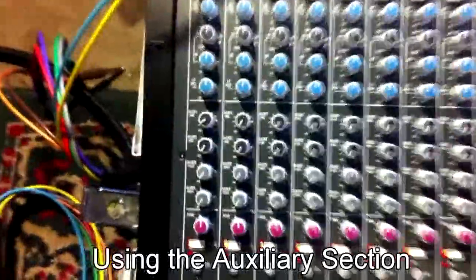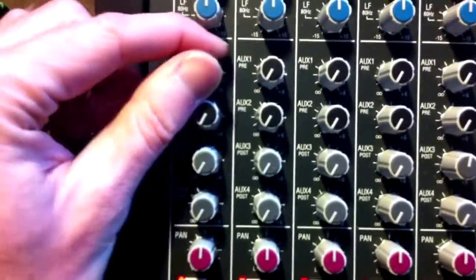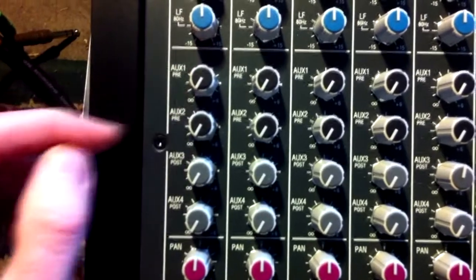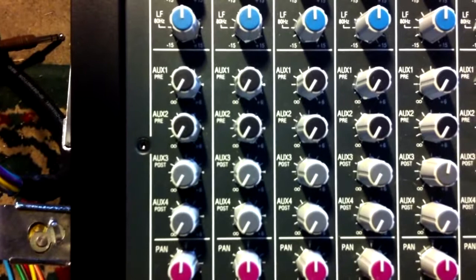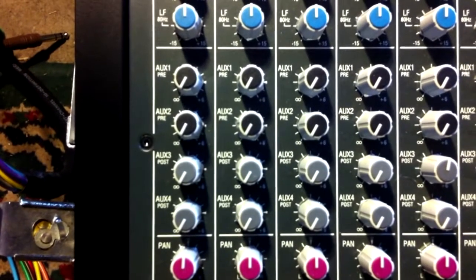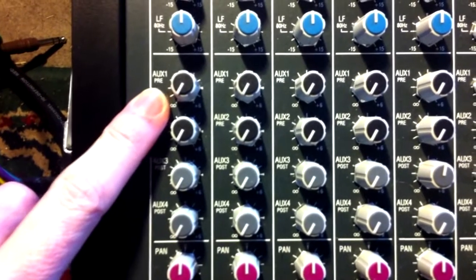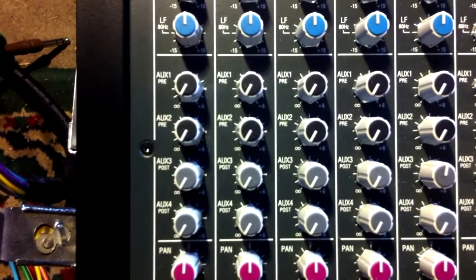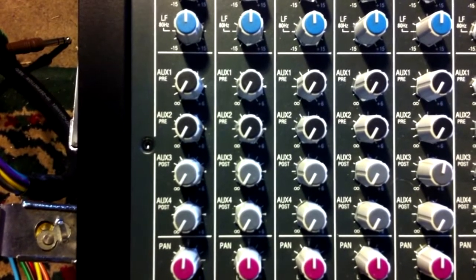Now for the auxiliary section. There's not much more to say than that they're all different volume controls. So you can treat them all just like the faders, except they will go to different outputs. Where it gets complicated is in the fact that many mixers are set up in very different ways. On this mixer, auxiliary 1 and auxiliary 2 are pre-fader. Generally when you see the word pre or post on your mixer, it means pre-fader or post-fader.